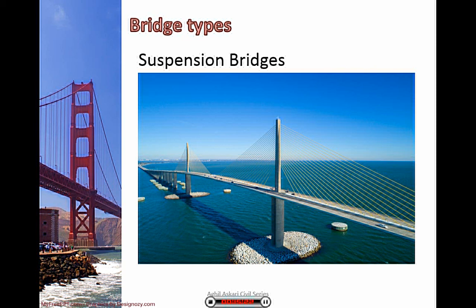This type of structure tends to be used for distances greater than those achieved with a cantilever bridge, but less than a suspension bridge. One of the main issues with this type of bridge is that the central connection of the cables can place horizontal pressure on the deck. Therefore, the deck structures need to be reinforced to withstand this ongoing pressure.